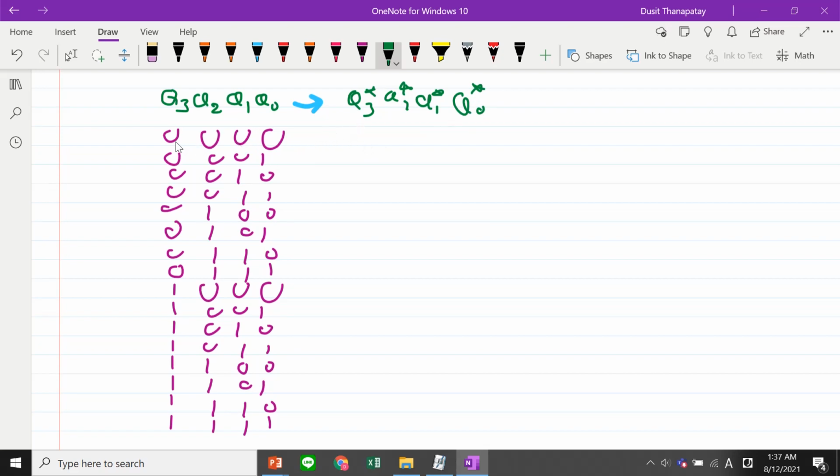So it changed from what? 0, 0, 0 when clock tick, it goes to 0, 0, 0, 1, right? And from 0, 0, 1, it goes to 0, 0, 1, 0. And the next state of 0, 0, 1, 0 is 0, 0, 1, 1, okay, and so on.